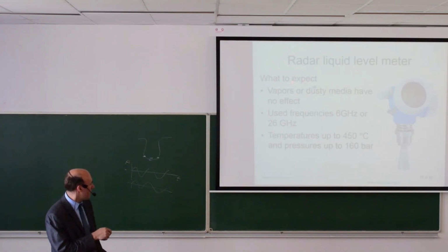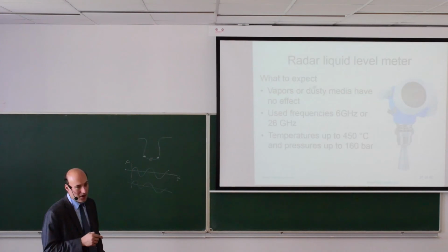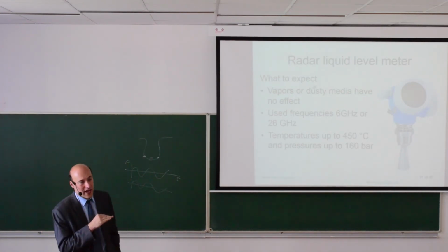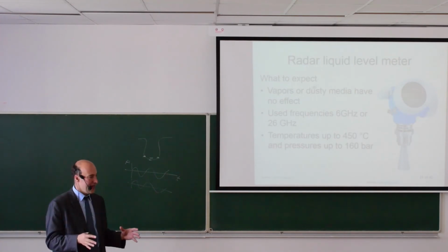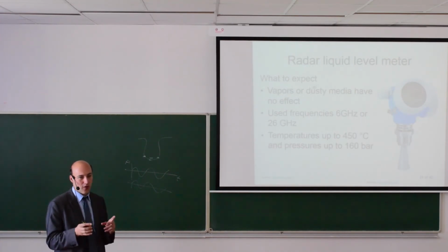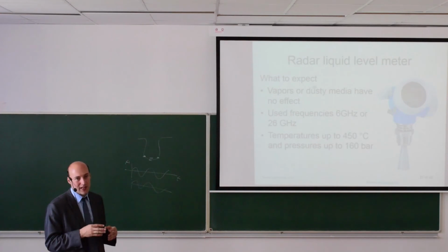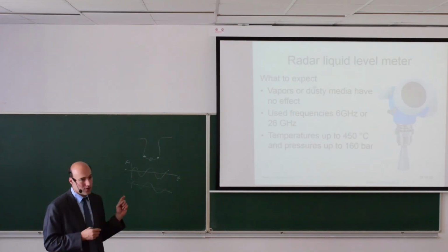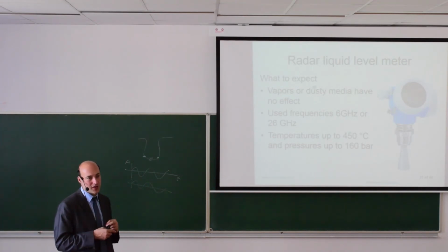It is not affected by vapors or dust. But what can affect it is the eventual barriers in the tanks. You may have barriers that reinforce the tank, you may have mixers, and from all this you may get reflections. So this may be a problem for the radar, and for the ultrasonic sensor as well.